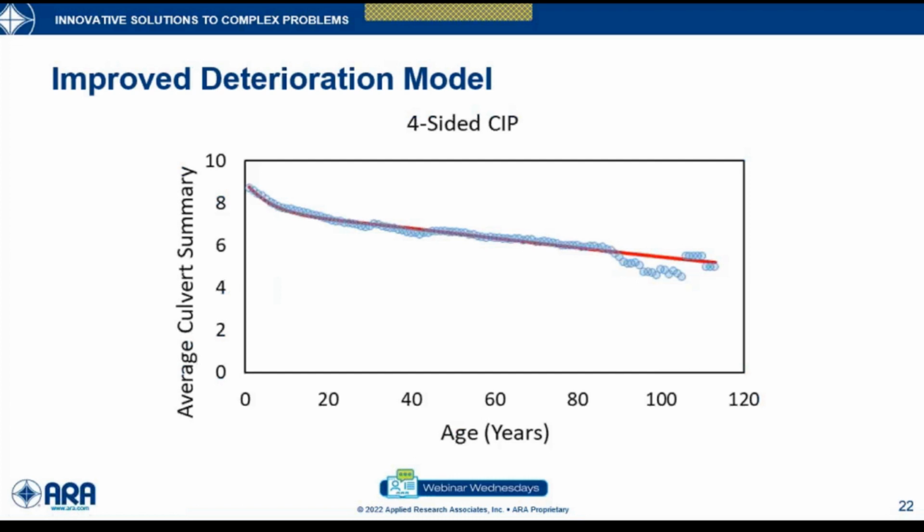Allowing for that in the Markov model follows from the understanding that this is a continuous deterioration process and the discrete condition scale is not the ideal engineering representation. Understanding that aspect and allowing some assets to go back to an improved condition actually improved our deterioration models and increased their flexibility to allow for that nonlinear behavior in one model.